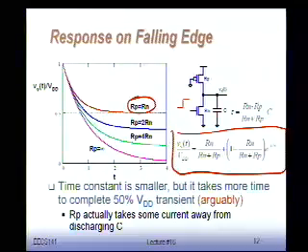It's the definition of what's your propagation delay. Okay? Definition of the propagation delay is the 50% point. Right? Now some people interpret this at a 50% point between 0 and VDD. While the other one said, no. It's a 50% point between VOL and VOH. So it really depends on what I'm connecting here.